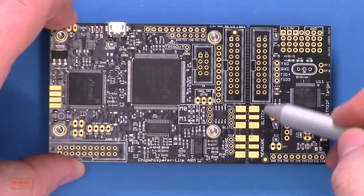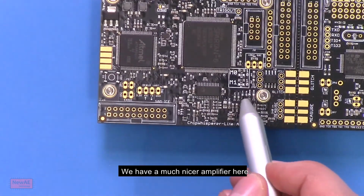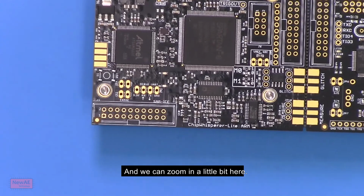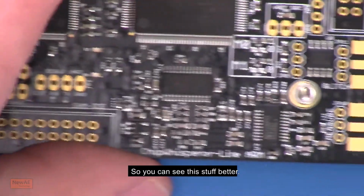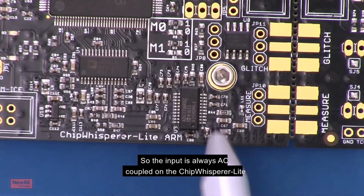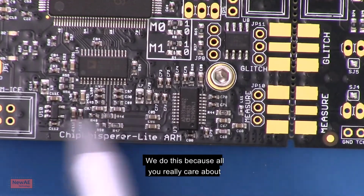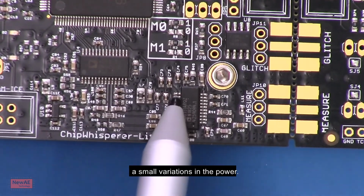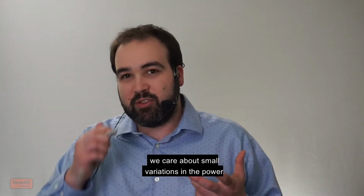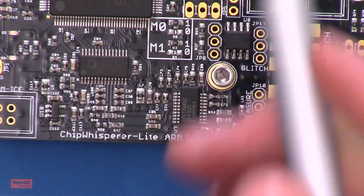Again, we have a target section here. We have a much nicer amplifier here. This is a low noise amplifier. We can zoom in a little bit here so you can see this stuff better. It's AC coupled, so the input is always AC coupled on the ChipWhisperer Lite, and the same on the Nano. We do this because all you really care about is small variations in the power. We don't care about absolute power. We care about small variations, so that's why we're using AC coupling here.